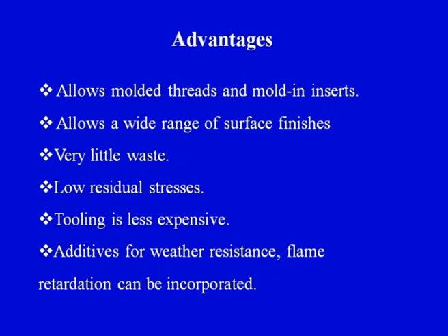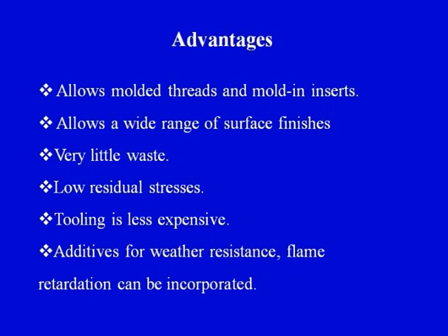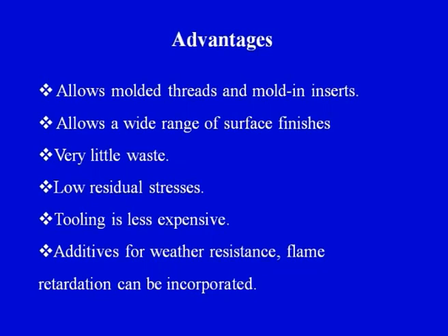Also you can see on your screen that the residual stresses that are developed are minimum in case of rotational molding. Also, once a mold has been made, it can be used for making a large number of parts. So the tooling requirements are not that expensive in case of rotational molding. Another advantage of the process is that additives for weather resistant flame retardation can be incorporated.